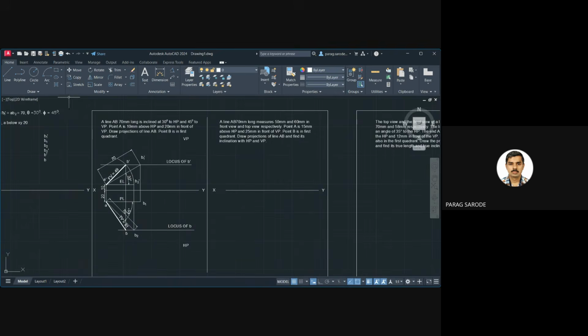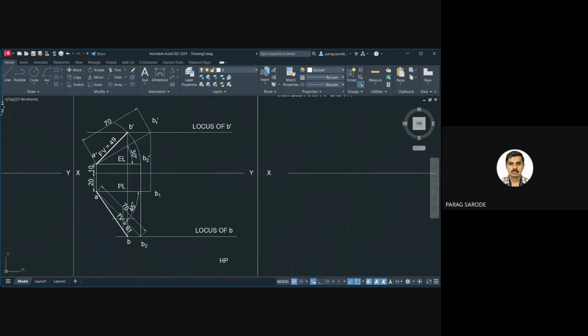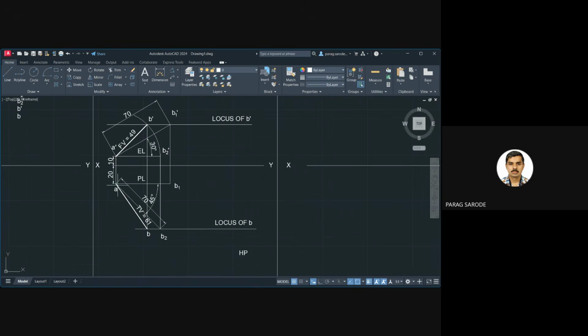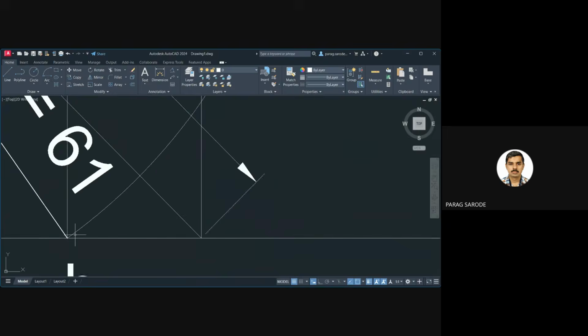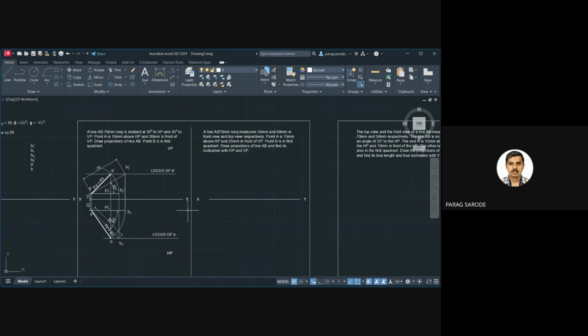Now, just to confirm this, I will show you whether the A B1 arc will lead to the same point. A is the center, B1 is this, but the arc always starts counterclockwise, so I need to press the control button like this and keep it held. Yes, it shows the same thing. Then once I click, remove the control button. You can see that it is intersecting the same point, even after enlarging. That means the solution is correct.